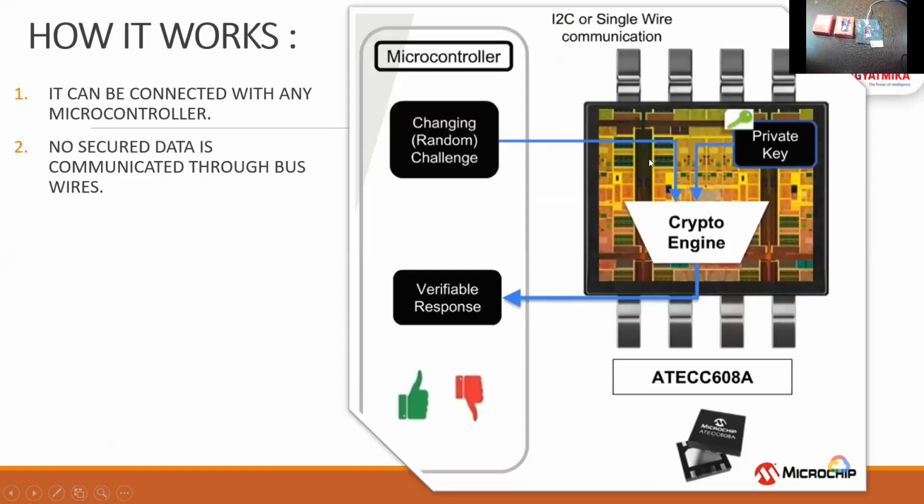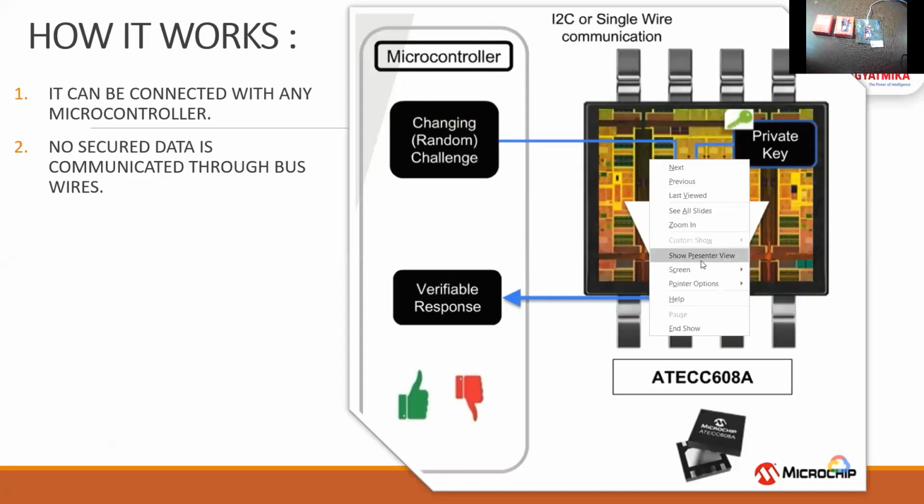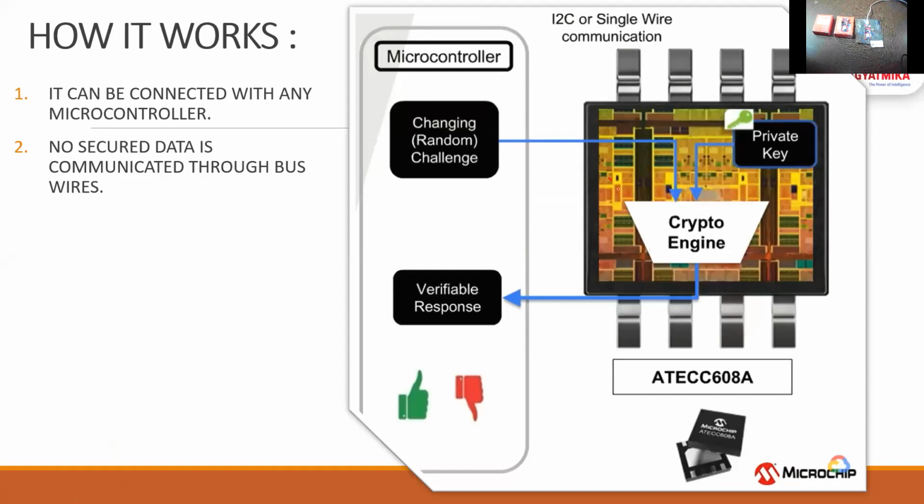So this is your ATECC hard crypto. This is your ATECC engine, and it has the crypto engine, and the private keys are in it. Whenever the microcontroller has to communicate with it, it will communicate over I2C or a single wire communication.